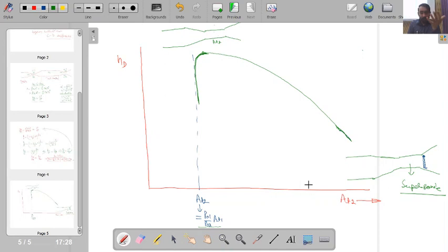So during the transient operation of this particular wind tunnel, what happens? We experience that at the nozzle section, whenever the flow is increasing, there is formation of a shock wave. Okay, and that shock wave has to first travel through the entire section and leave that section in order to reach a steady or desired Mach number condition.